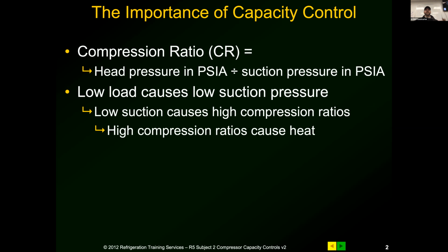The difference is what state the refrigerant's in. If you've ever run your fingers down a condenser coil and you get two-thirds, one-third, you know what I'm saying there? It feels two-thirds hot, one-third cooler. That's where it's changing phase, going from a high pressure vapor to a high pressure liquid. Depending on the state of the refrigerant, it's either de-superheating or subcooling. We can talk more to that when we go more into superheat and subcooling in the beginning and advanced classes.